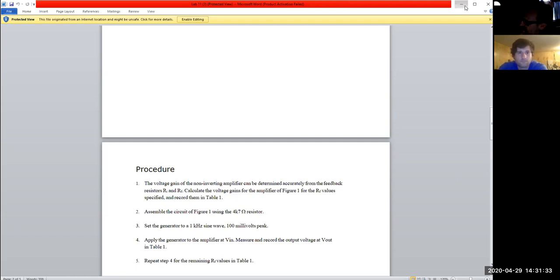It's basically the input, and then what kind of little transformer you got on that thing. And usually what fails on those is the reference voltage, believe it or not. I used to fix quite a few of those. They're a pain in the ass, but you could always refurbish a power supply and get it going again.